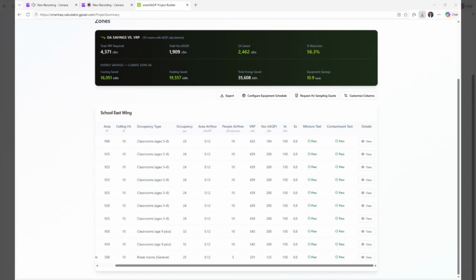And then if you need it, each of the rooms in the project now have a summary over here on the DC limit tests. If you want to understand the levels of the contaminants in the steady state after you've done this design with the air cleaner, you can see them. They're all green because they're all less than the design limits. But this is a helpful summary if you ever wanted to include it. It's not necessary for documentation purposes, but it's helpful if you want it.